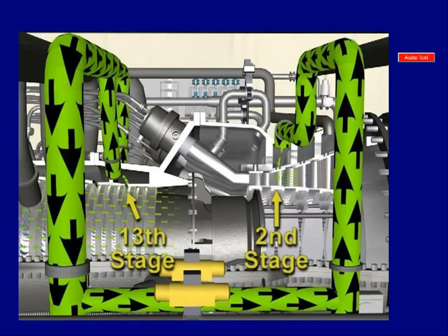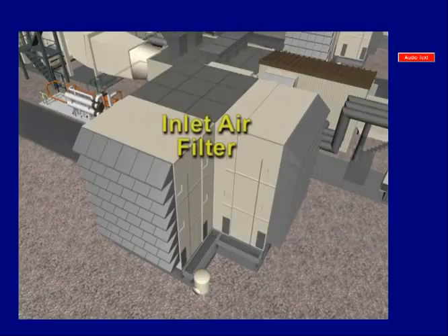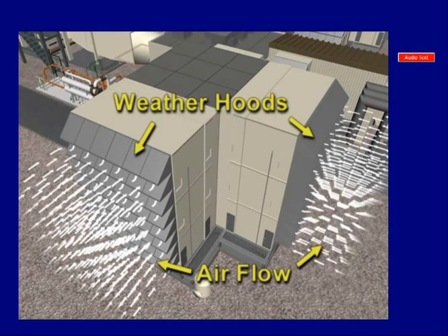Welcome to Book 1, Chapter 1. This chapter will overview the combustion turbine flow path. The incoming air to the turbine flows through a series of filters on its way to support combustion. Ambient air first enters the filter housing through a weather hood and screen that protects the filters from the effects of rain, sun, and debris.